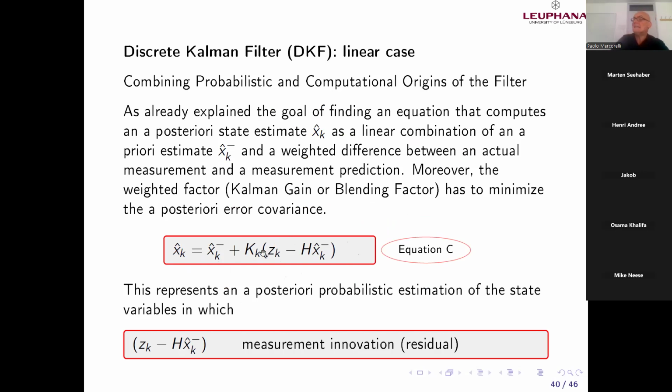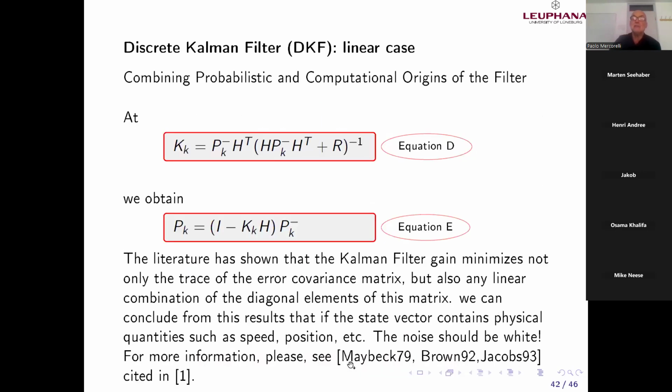Now we can see that K is an adaptive weight of what? Of this difference. In the literature, we call this difference, written here, innovations. Try to do at home the consideration if Q is small and R is small. It is easy to see because if Q is small, K is very small, theoretically zero if we trust totally the model.